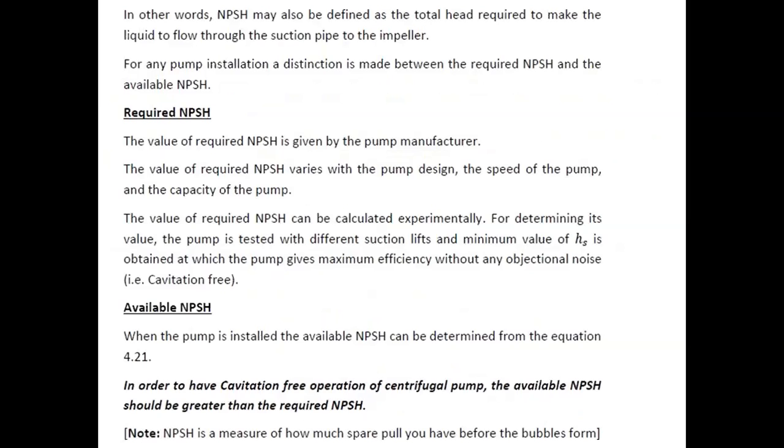In other words, NPSH may also be defined as the total head required to make the liquid flow through the suction pipe to the impeller. For any pump installed, a distinction is made between the required NPSH and the available NPSH.